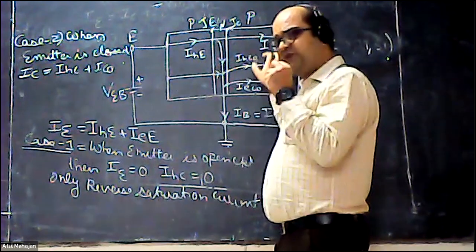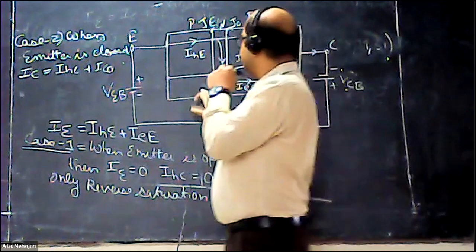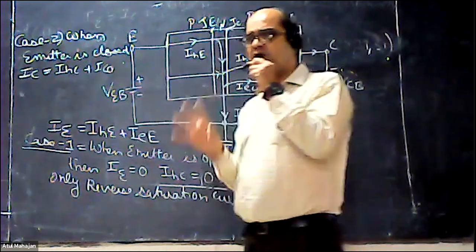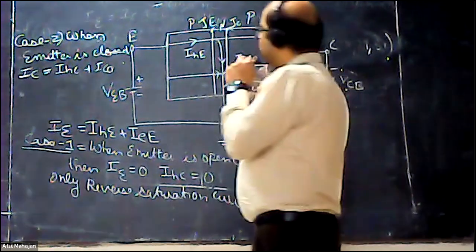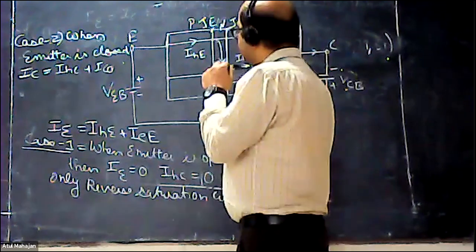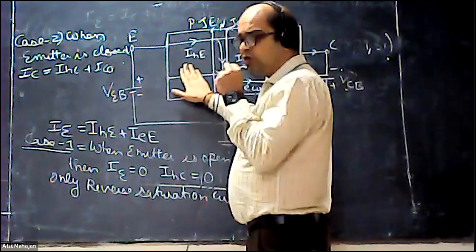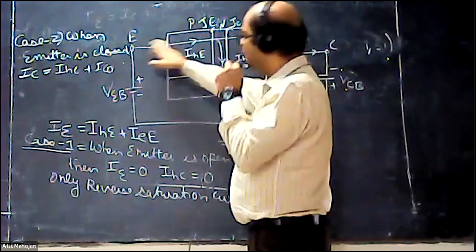It also has a concentration of holes as majority carriers, and electrons are there, but only as minority carriers. So first of all, the current being generated inside this transistor is because of this hole concentration, these majority carriers, because it is forward biased.